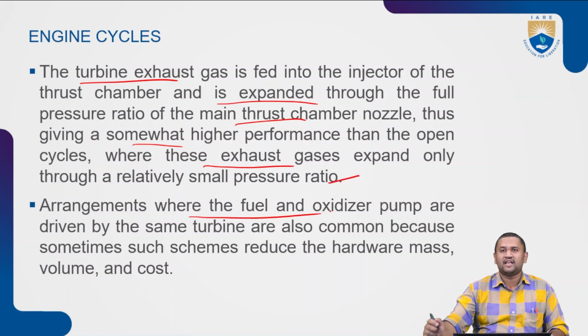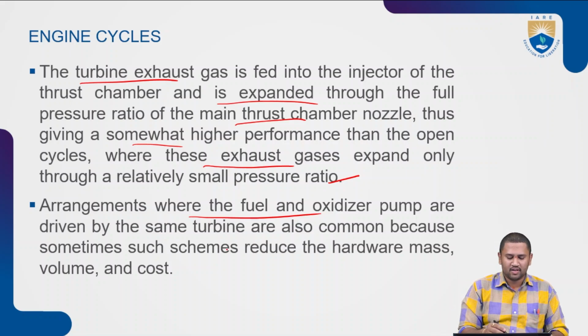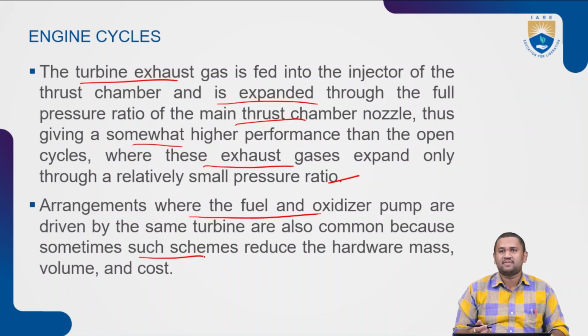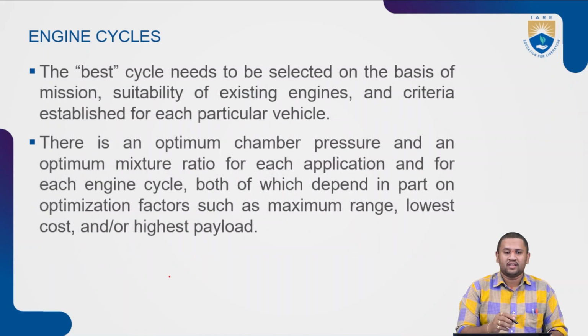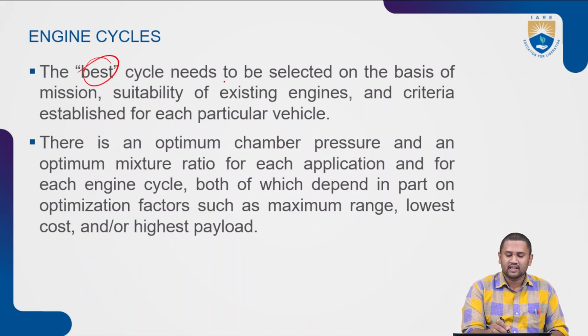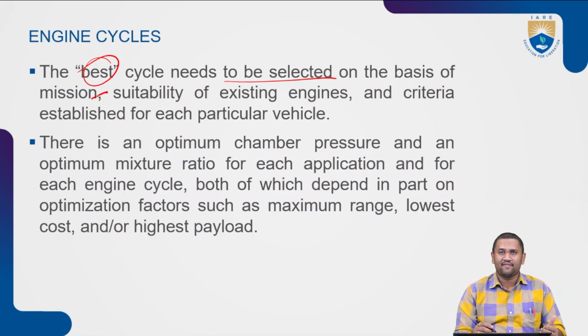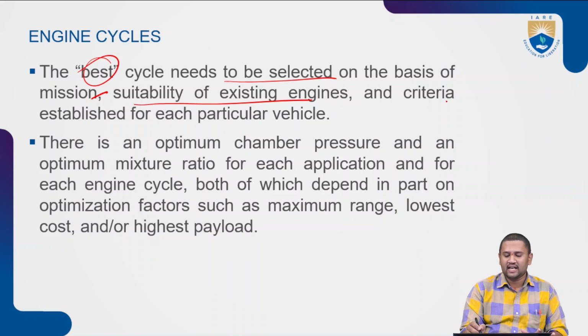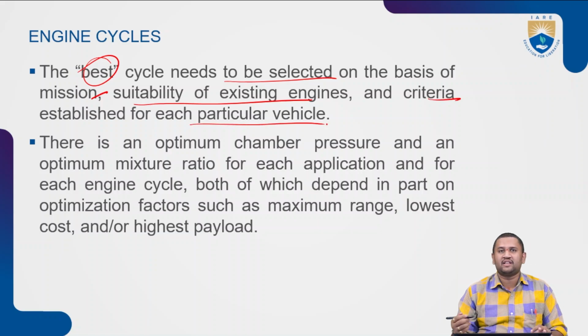Arrangements where the fuel as well as the oxidizer pump are driven by the same turbine are also common because sometimes such schemes reduce the hardware mass, volume as well as the cost. The best cycle among these should be selected on the basis of the mission that we plan for, the suitability with respect to the existing engines, and the criteria established for each particular vehicle.